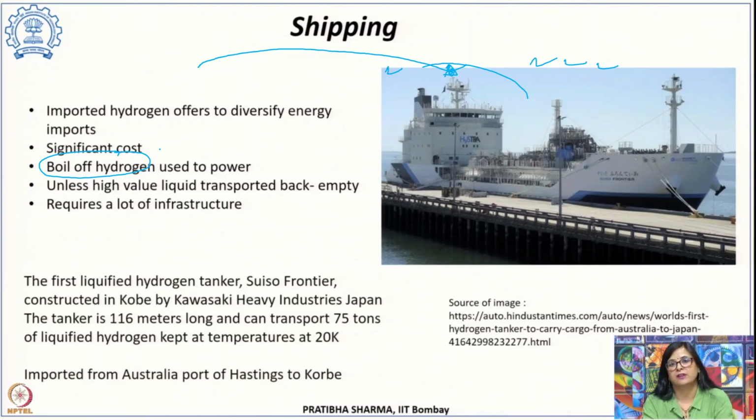At high temperature, the temperature rises inside the liquid hydrogen, the liquid hydrogen vaporizes, and the pressure becomes high. To avoid boil off, as you have studied, there is some extra vacant space in the liquid hydrogen storage tank to accommodate such effects.